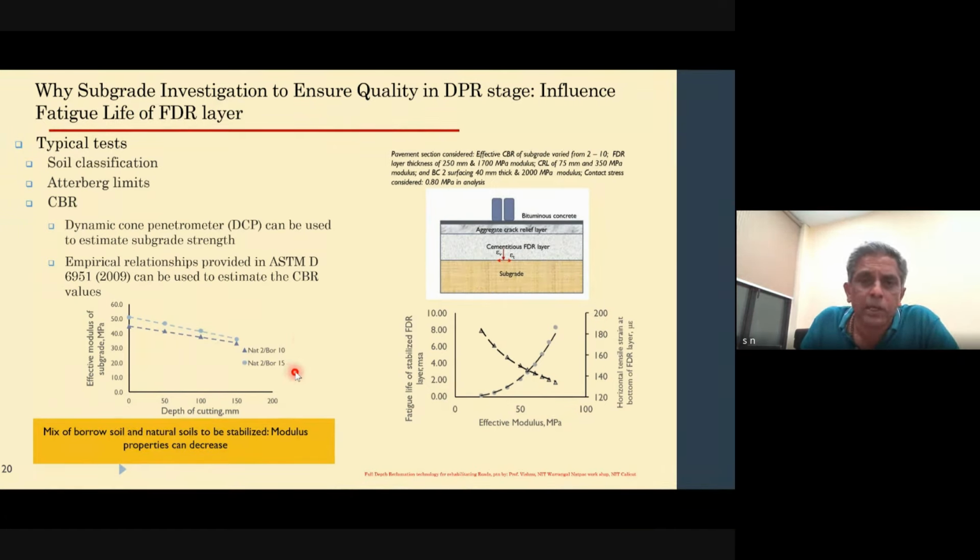In terms of sampling, few things to remember: visual observation, that is very key. Distress identification. Drainage issues is a very easy thing that can be visually identified. Uniformity of the section can also be checked by using multiple pits. Now, you can determine a representative section and how many mix designs you may have to make, considering the variability in terms of the sectional thicknesses across the length of the road. Very difficult to identify a representative section, but still some part of it is possible, especially drainage issues can be easily addressed by visual inspections.